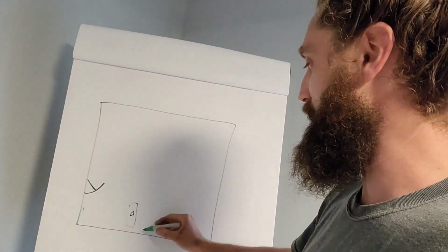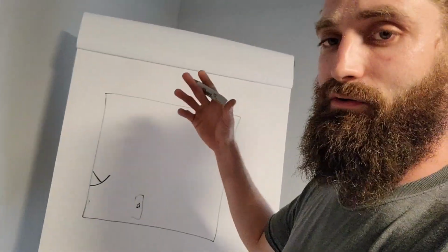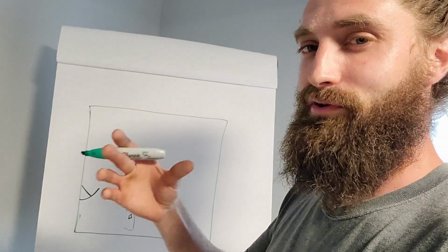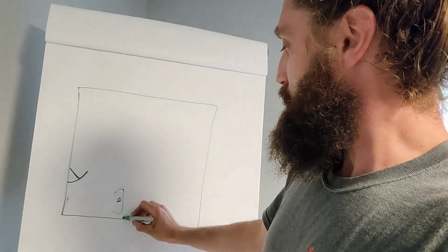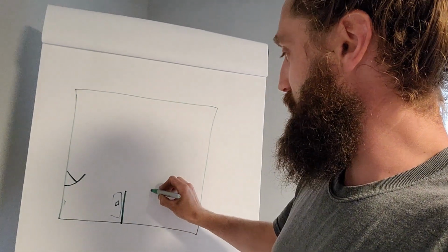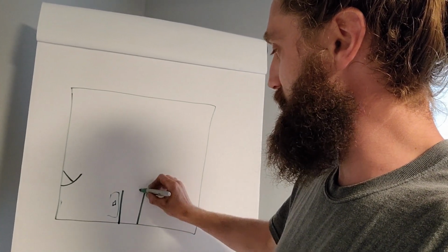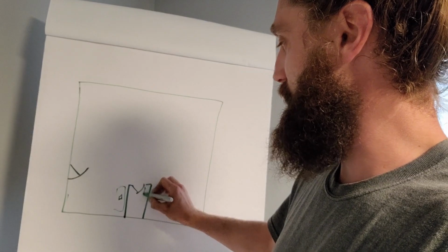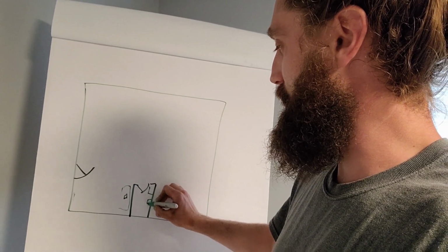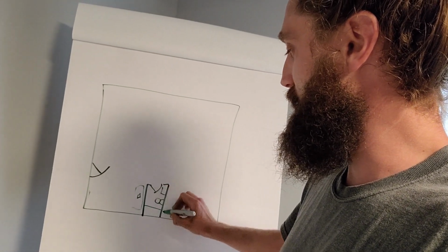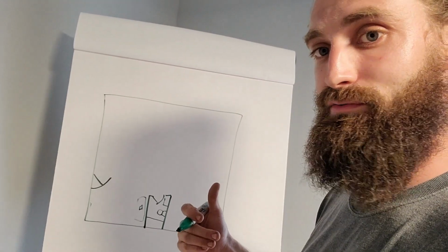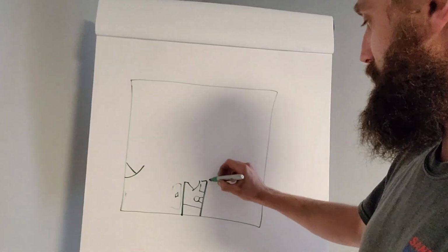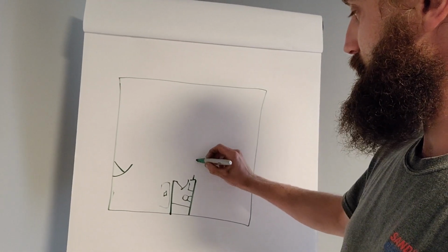So here, what I'm doing is putting on the computer, on the piece of paper, pieces of furniture where the chances of them being moved are pretty slim. If you've got a big china hutch, or a bedroom where you know the only place a bed is going to go is against this one wall, we don't want to throw a supply duct right under where that bed's going to be.